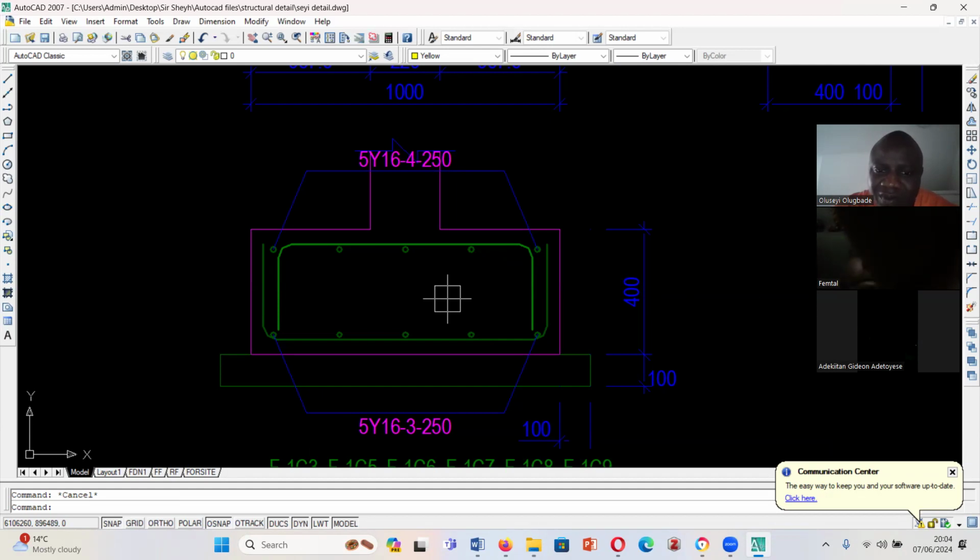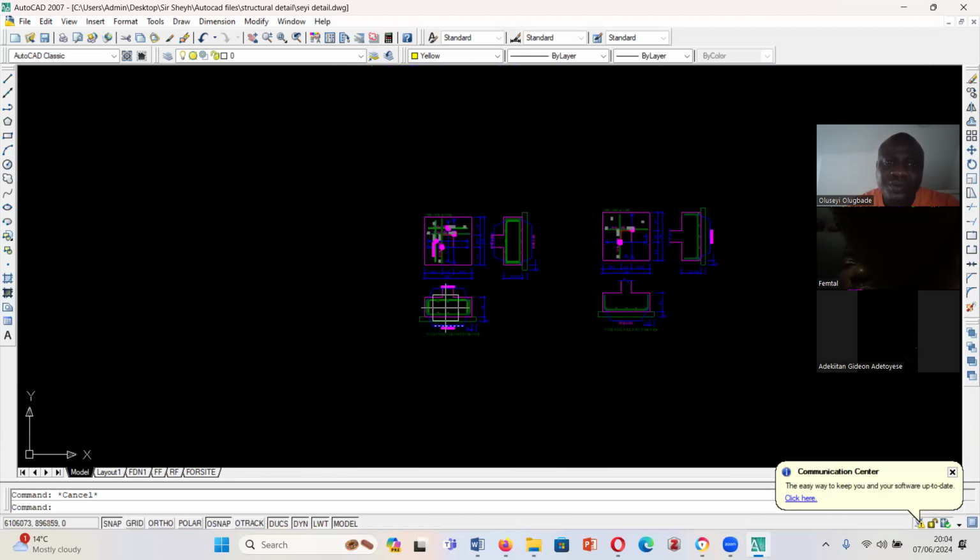Yes, sir. If you say the purpose of blinding is to avoid corrosion, I would say that it is very correct. But for your biscuit, the purpose is so that you can have your concrete cover. Generally, the size of your concrete cover determines when your steel will begin to corrode also. So that was why I said you are in a way right the other time too.